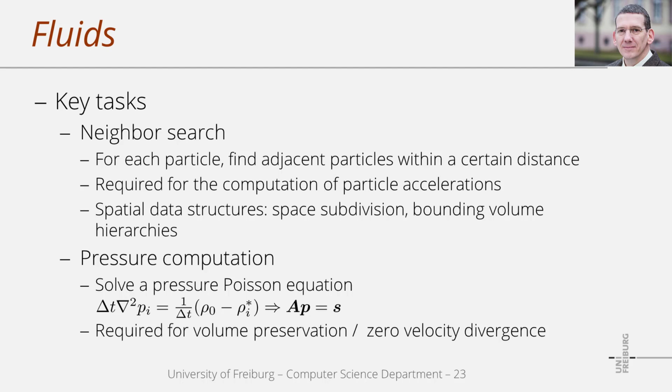Now, the problem is that we typically have large numbers of particles, and we also have the problem that the spatial relations between fluid particles change over time. This means that the particle neighbors have to be recomputed for each single simulation step. And again, generally we have many particles and also many simulation steps. In order to accelerate the neighbor search, we use spatial data structures that typically base on space subdivision or bounding volume hierarchies. Now in the course, I will discuss various implementation aspects in the context of space subdivision.